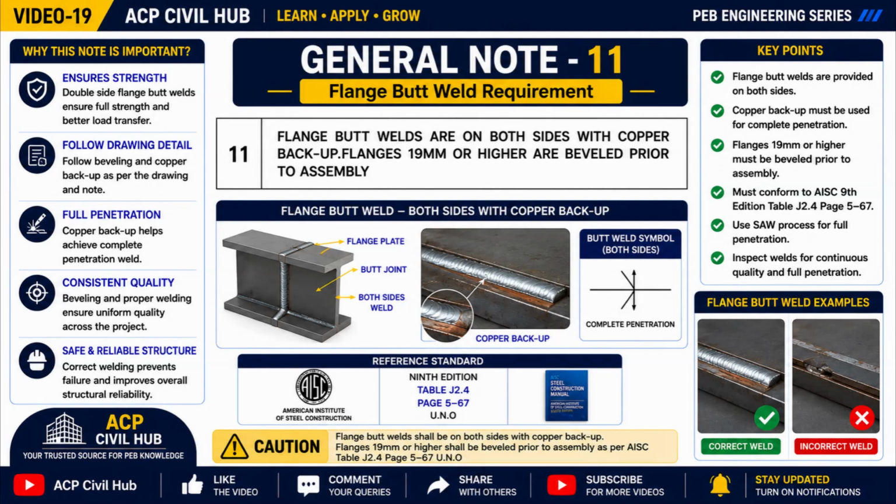A copper backup bar is placed beneath the joint during welding. It supports the molten weld metal, prevents burn-through, and helps produce a smooth, high-quality root weld. The weld is then completed from both sides of the flange, creating a strong and continuous connection capable of safely transferring tensile and compressive forces.